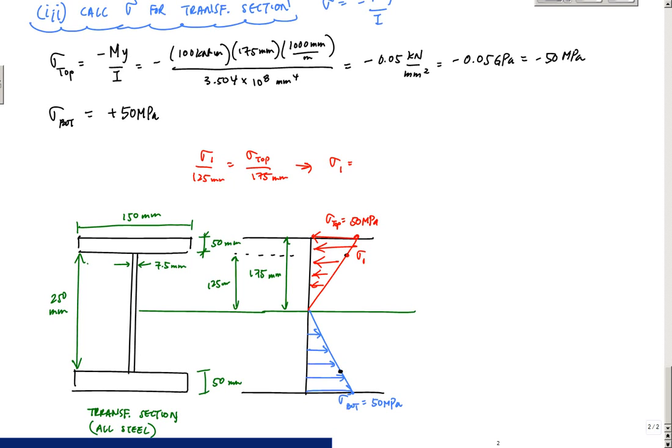That's going to be some number, which is 36 megapascals right there. Okay, so 36 megapascals. It's the same thing down here: this other point is also 36 megapascals, right where I transition from this point in the flange to the quote-unquote web, which is wood transformed into steel.